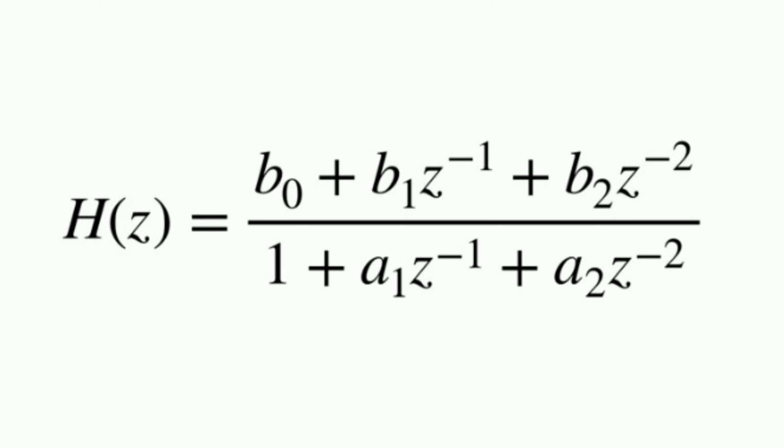The coefficients in the numerator are the zeros b0, b1, b2, and the coefficients in the denominator are the poles a0, a1, a2. Please note that a0 is the coefficient associated with the filter's output, and to normalize a filter, one needs to divide every other pole coefficient by a0 so that a0 becomes 1. MiniDSP will accept only normalized biquad coefficients.